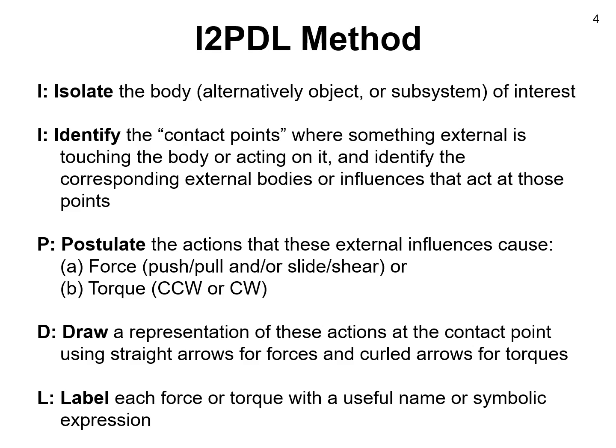We're going to draw a representation of these actions at the contact points using straight arrows for forces and curled arrows for torques. And finally, label. We're going to label each force or torque with a useful name or symbolic expression.